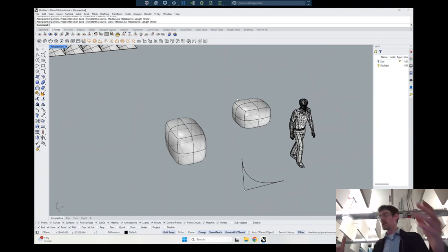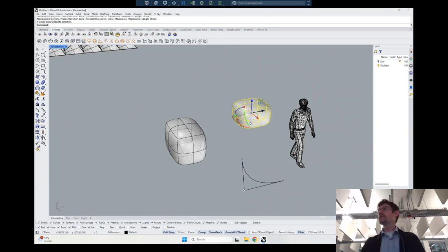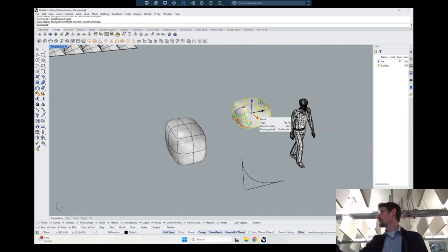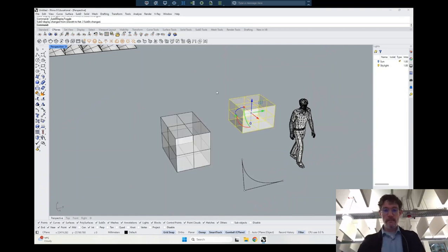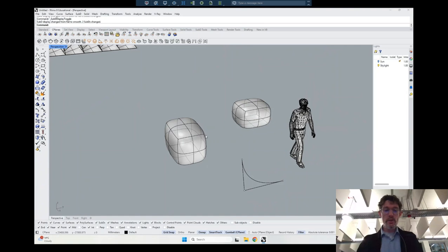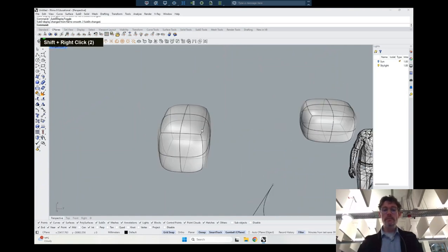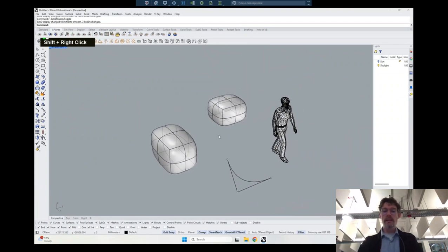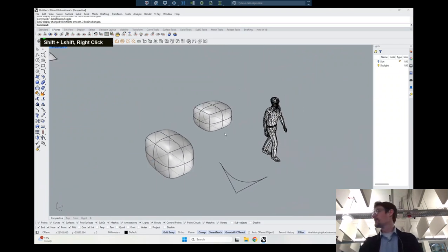It's got 3 dimensions. So effectively, rather than click on this thing and then type F10 to find my control points, I can switch between seeing the control points using the tab key, and then the smoothed version of that thing. The tab key is really super helpful in that. But this is where most people, when they're using sub-D or mesh-based modeling, end up making weird strings of chewing gum and spaghetti.